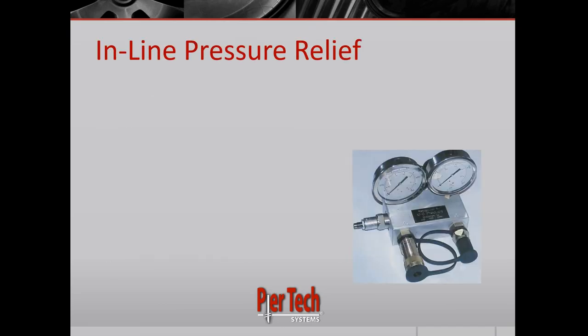All right, next I want to introduce the pressure gauges. So in the previous couple examples, we determined what the minimum required installation torque is. And the units for that are foot-pounds of torque. If you are using pressure gauges, your units are PSI. So we have to have a conversion to go from torque to pressure, or from pressure to torque. So this is where this step comes in.